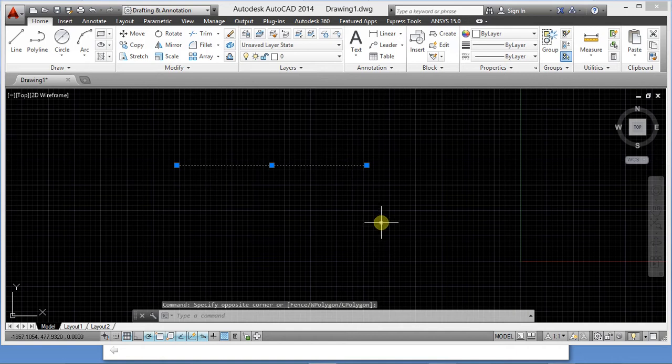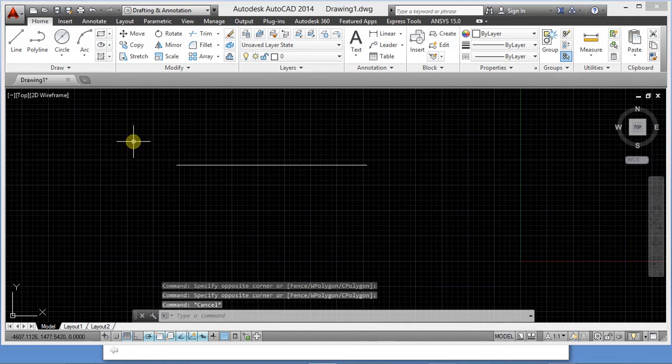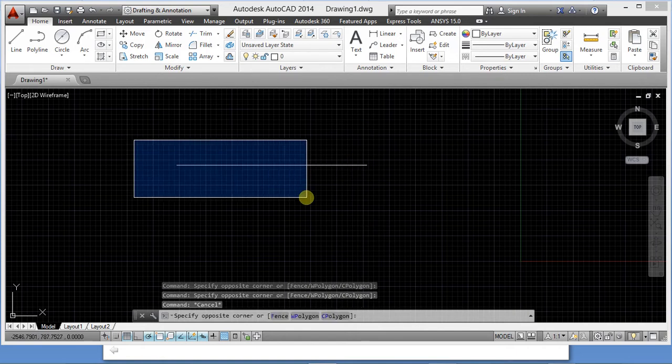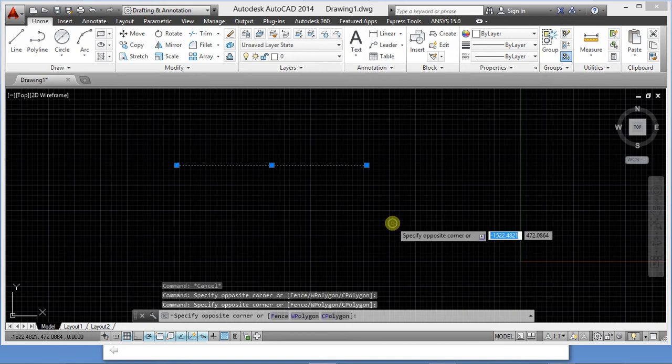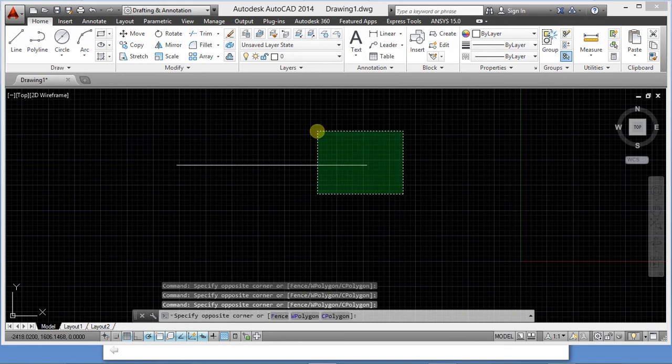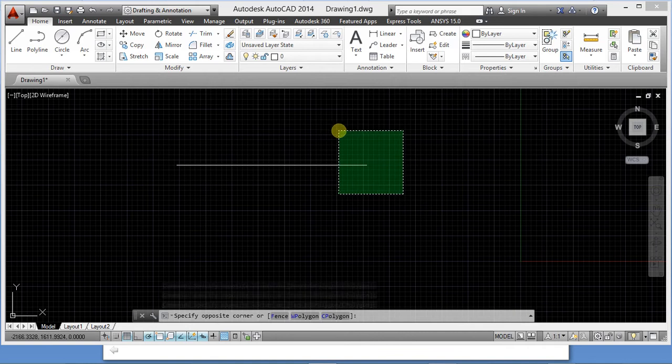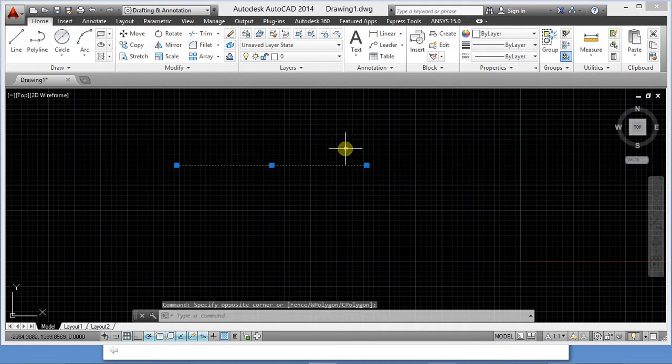Okay, unlike what I did from left to right, where if I select it halfway, the line will not be selected. You need a total selection before the line can be selected. But if I select from right to left, it will give me a green selection area, and I just need to touch that part of the sketch on my workspace for it to be selected entirely.